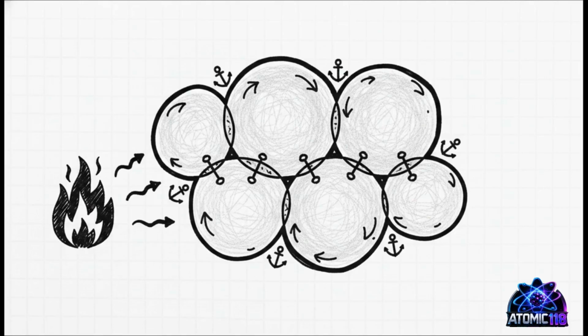In this one fascinating study, researchers took medium manganese martensitic steel and heated it to 820 degrees Celsius. At first, the austenite grains were an ultra-fine 3.98 micrometers. But here's the crazy part. Even after holding that intense heat for a full hour, 3,600 seconds, the grains only grew by 1.47 micrometers. This ridiculous resistance to coarsening happens because those tiny vanadium carbonitride particles sit right on the borders of the grains, physically blocking them from expanding.